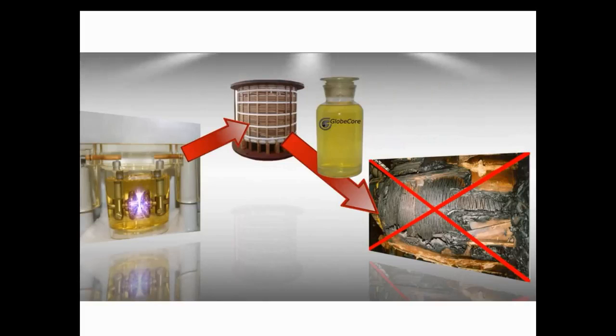We've got to know that paper and oil oxidize and age. If you take a piece of paper and pull it over, you make a test for mechanical strength or for degree of polymerization, DP. When the paper is new, DP is 1200. As the paper gets old, this value becomes about 200.